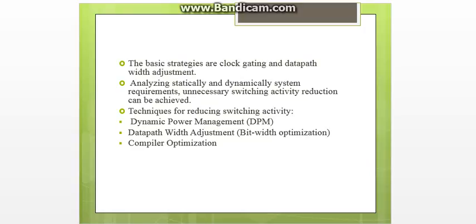First is the dynamic power management. It dynamically reconfigures the system to provide the requested services and performance levels with a minimum number of active components or a minimum load on such components. The fundamental premise for the applicability of DPM is that systems and their components experience non-uniform workload during operation time, and that it is possible to predict with a certain degree of confidence the fluctuation of workload. There are two power reduction methodologies with idle modes: voltage scaling with frequency scaling, and clock gating.